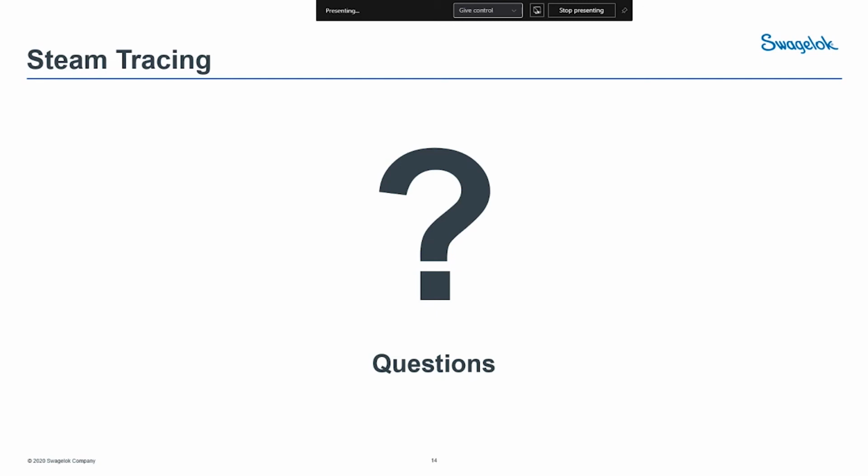Doesn't matter which one you actually pick. Yeah, so I think the big thing you've got to look for is flow rate and CV. So you get back to the CV sizing, and for more information on that, we've done a couple webinars on sizing, or reach out if you guys have questions. I think the ball valve's a much better option for just straight shut off, on and off.